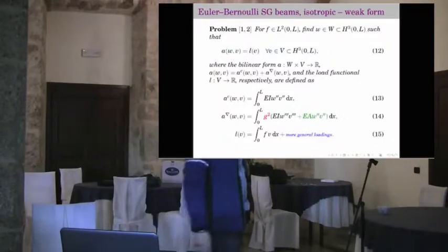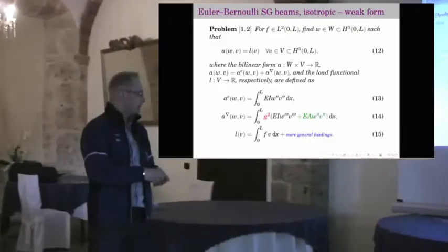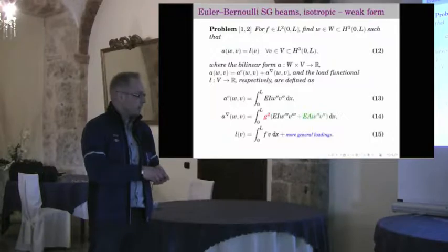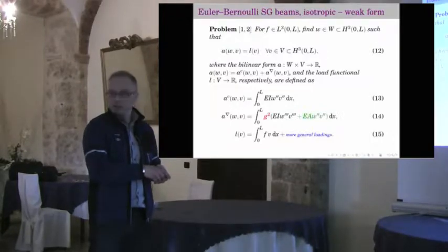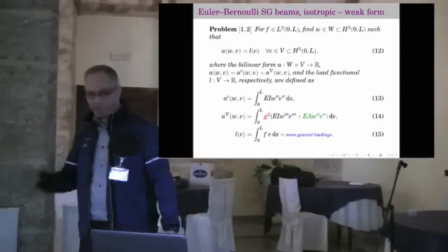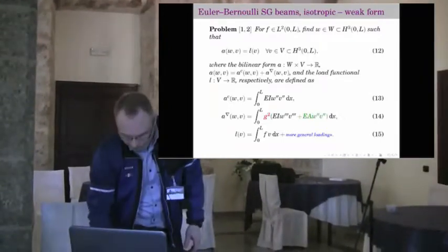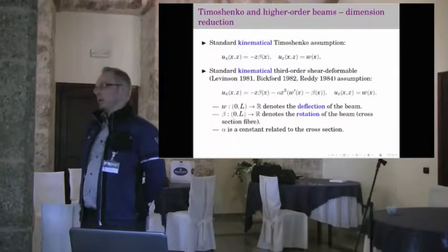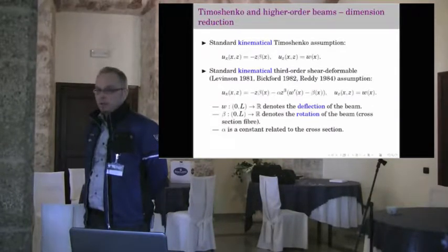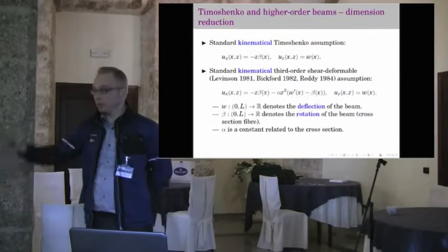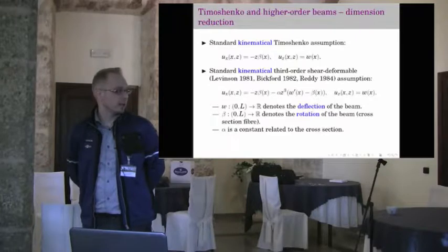You can see that we have here the higher order gradients in X, and because of the higher order gradients in Z direction, we have this term, which is the stiffening term that one can always see in these beam formulations of generalized continua. Actually one can see those also in modified couple stress theory and microdilatation theory and others. You can see, not the one that Yuri was presenting.